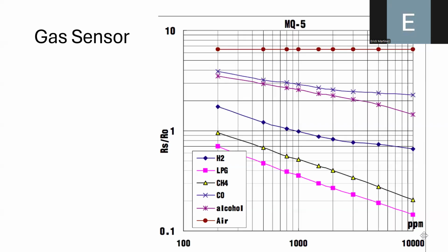So you need to perform this calibration under controlled conditions in order to have a rough estimate. In fact, I spent about 2 weeks trying to calibrate one of these sensors to measure alcohol, and it was a mess. It's quite complicated. These sensors are good only for detecting, but if you want to find the equation that fits this data or this behavior, it's very complicated, you know?